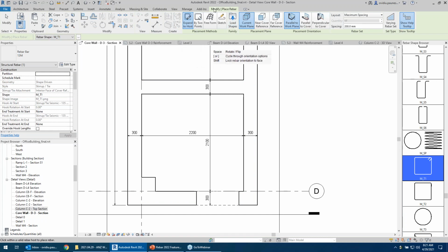I've clicked the rebar command, and now I have some options to place. Expand to host is the current option that we've had so far. It takes the selected rebar shape and expands it to fill the host as I am hovering inside of it, like you can see here. Of course, this does not offer the best results in all situations. For example, if I want to place a stirrup at the intersection of walls, I have to do a bit of adjustment.